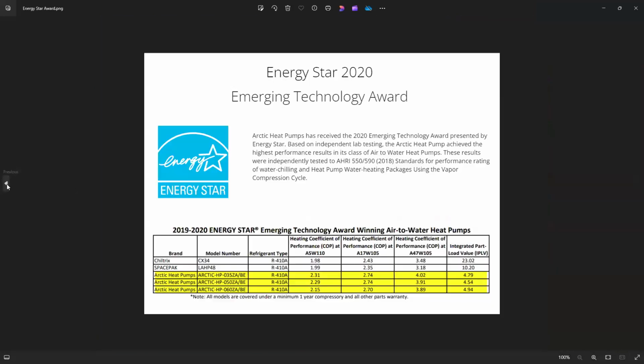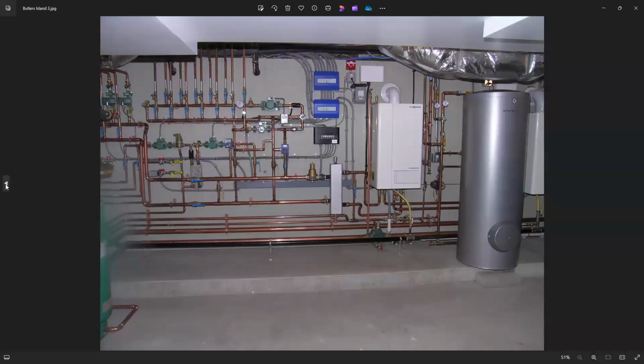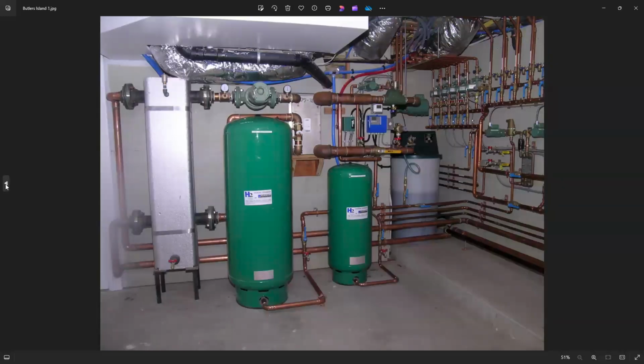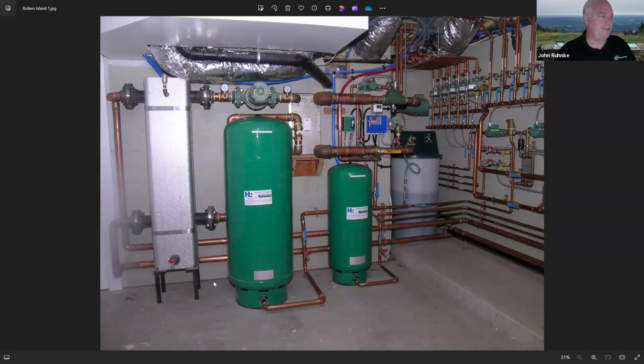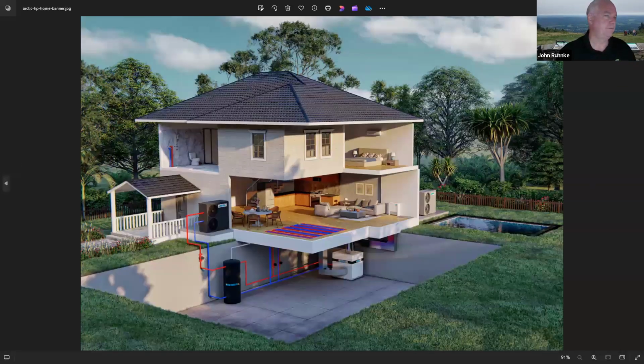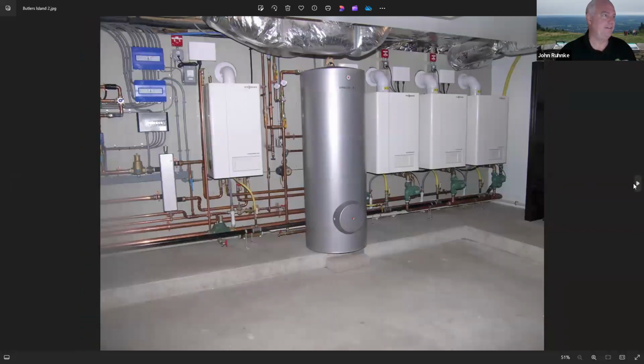John, could you go back to the picture with the snow melt system and explain some of the components, like the big silver one? Go back one. This one? Yeah, what is that? That's a low loss header. That creates isolation from the boiler system, which pipes directly into this on one side, and what's pumped out into the system out in the field, out in the driveway, which I didn't take a picture of. So basically it isolates.